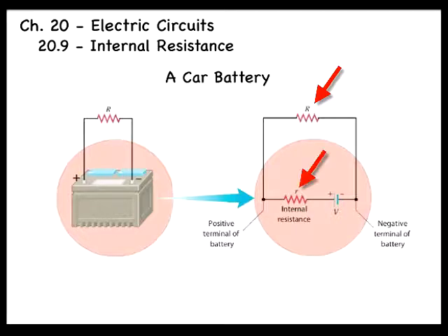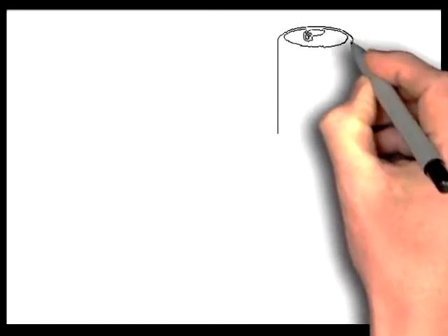with the internal resistance. The internal resistance of a functioning battery is typically small, several thousandths of an ohm for a new car battery. Nevertheless, the effect of the internal resistance may not be negligible. Here we show a simple example that illustrates that when a current is drawn from a battery, the internal resistance causes the voltage between the terminals to drop below the maximum value specified by the battery's EMF. The actual voltage between the terminals of a battery is known as the terminal voltage.